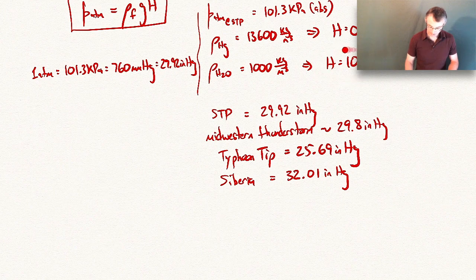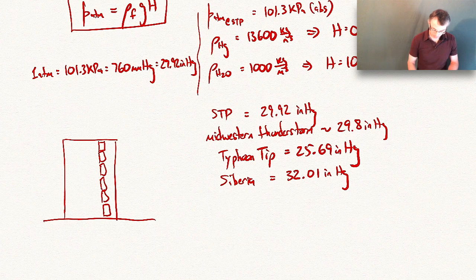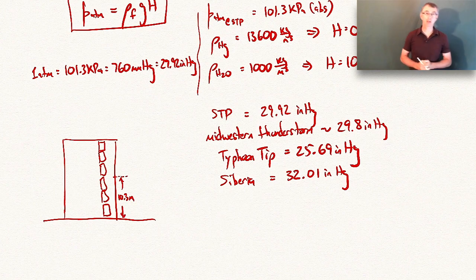Okay. Let me say one more thing before we move on to manometers, and this refers back to the barometer measurement. If we used water as the working fluid at atmospheric pressure, the column of water would be 10.3 meters tall. So let's imagine the scenario. Let's say we have a tall building that's multiple stories, so here's 3 stories, 4, 5, let's say 6 stories tall. Now 10.3 meters gets us to about 3 stories, maybe a little more than that.